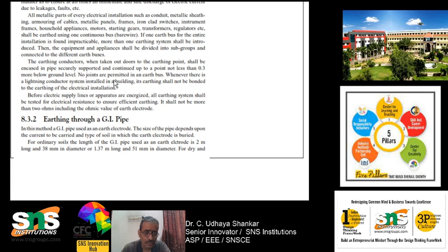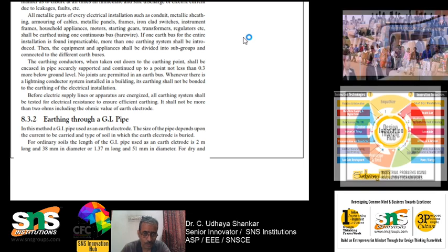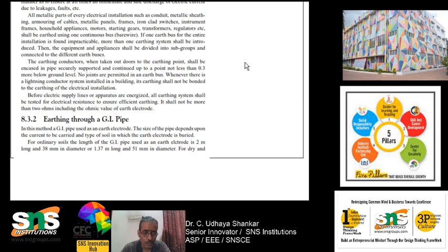In order to avoid that, we will be doing the earthing of the metal parts in that particular equipment, so that whatever electrons are flowing inside it will not pass through us, but will go directly to the earth. So we will not observe the shock if earthing is properly done. Why it is done is to ensure immediate and safe discharge of electric current at all times, and also that leakages and faults should not affect us.